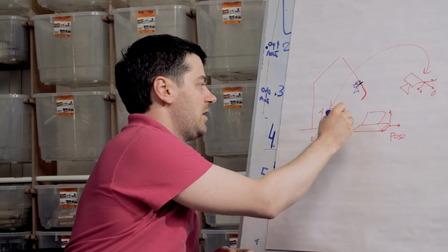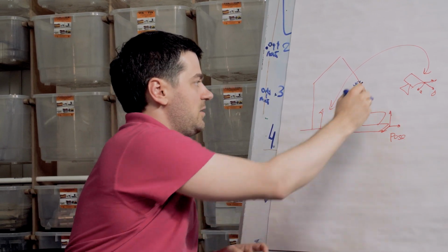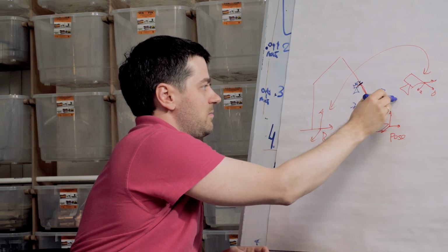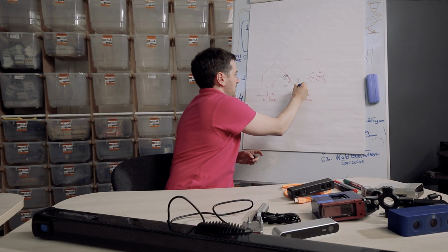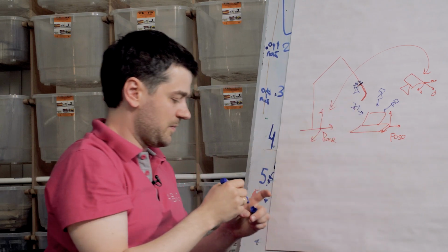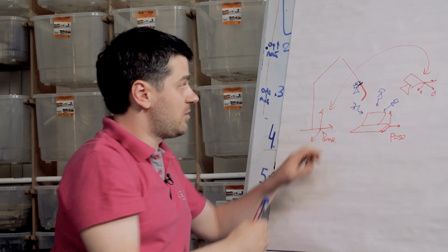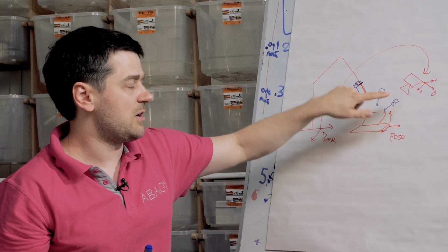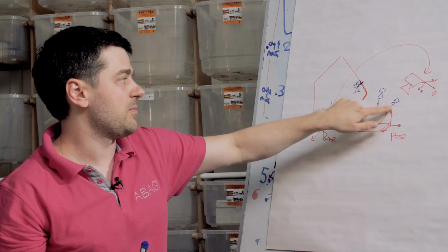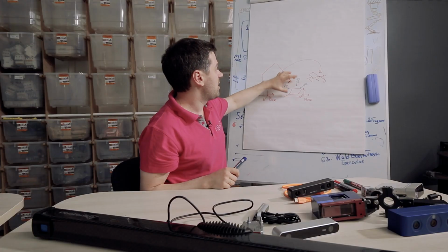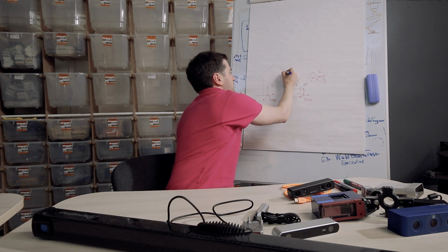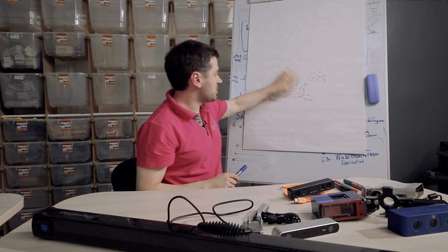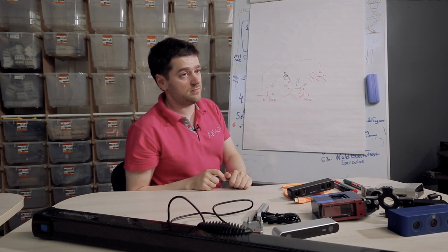So we can put a calibration object here and shoot it from different poses. Then storing the position of the flange and the position of the object in every image shot from these positions, we can recalculate this transformation from the flange to the camera. And this procedure is called hand-eye calibration.